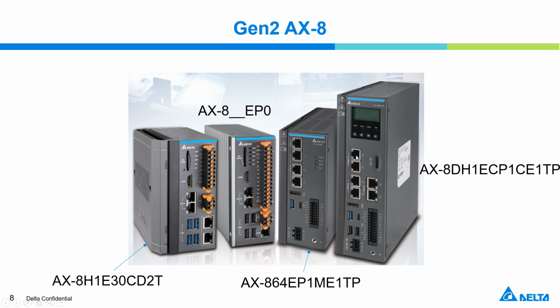And you can see that here it supports 4 LAN ports, and on the right side it has 2 EtherCAT ports, and the built-in I/O supports the FPGA, meaning it's the high-speed I/O. It can also support incremental encoders and absolute encoders, and this encoder is shared with the IS45 function, and it can also support the high-speed counter.